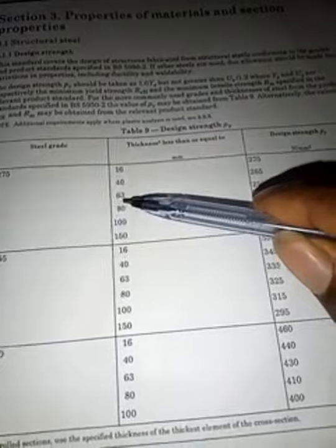Right? So from our Table 9, we've now agreed it is S355. We've gotten our thickness. Our thickness was less than 16. That means our design strength for our steel will be 355 Newton per millimeter square. So once you are done with this, you close your Table 9. You are going to the next table. The next table we are looking for is Table 11. So this is Table 9, Table 10, and for our classification of cross section, we find Table 11. Table 11 is giving us the width to thickness ratio of our different sections. For section classification, it is this Table 11 that gives you your final answer.